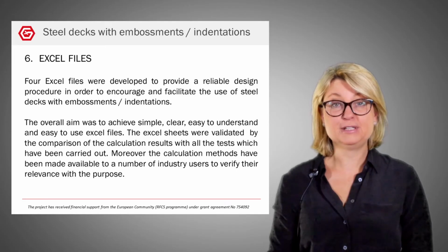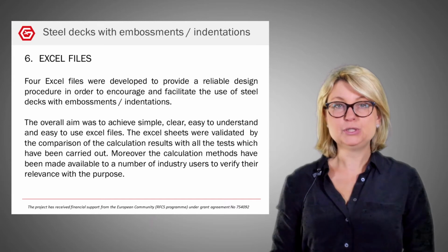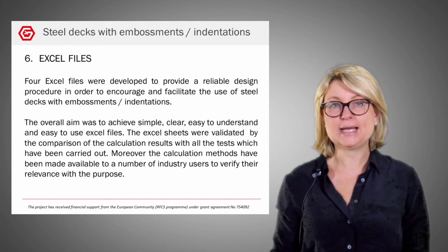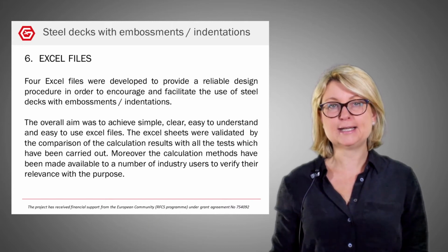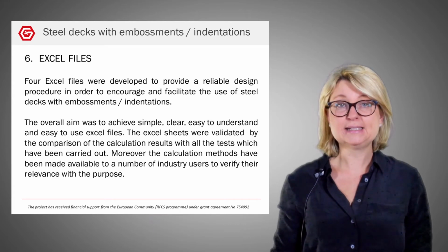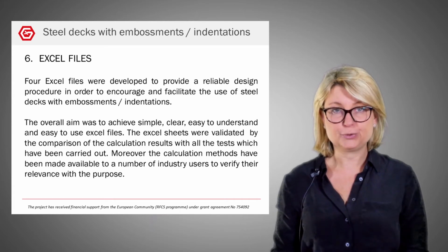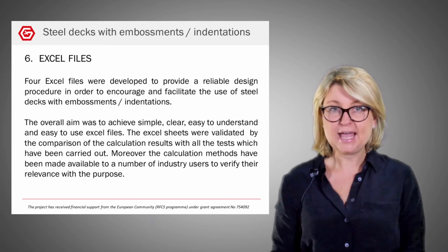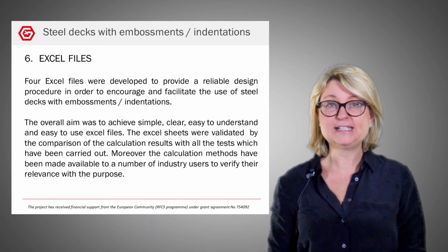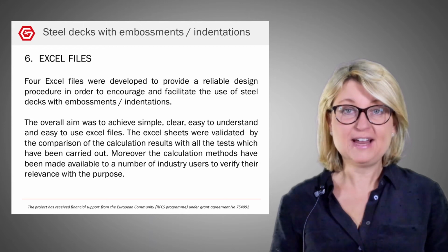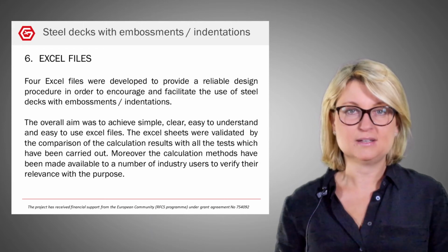For the final part of this presentation, I would like to introduce the Excel files which were implemented to calculate resistances for steel decks with embossments and indentations. These Excel files were developed to provide a reliable design procedure and to encourage and facilitate the use of these products. These files were validated by comparing their results with the results of the testing.